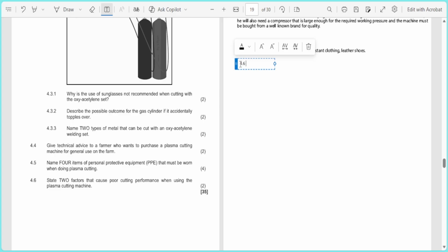Most plasma cutting problems normally trace back to air quality and pressure. Water in the line causes erratic arcs and ruins consumables fast. Worn parts are the number one cause of poor cuts when it comes to cutting with a plasma machine.